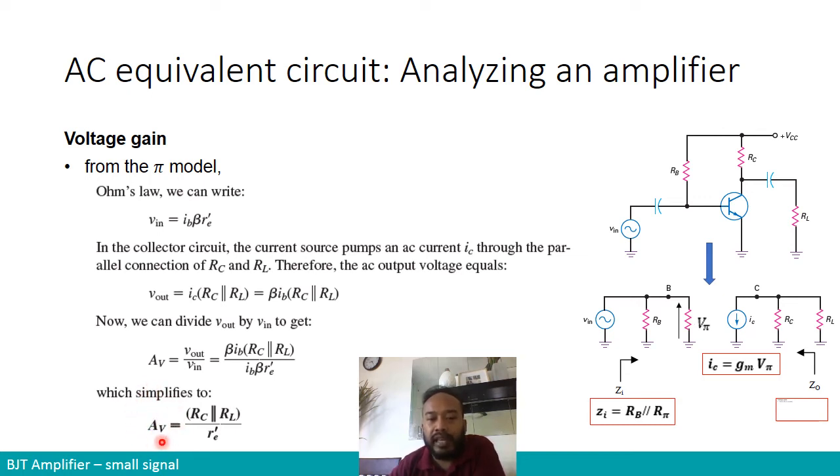And then of course the gain of the amplification, the voltage gain, is just the ratio of V output divided by V input. So this is what we get over here. Depending on which parameter is given, it might vary, but here it shows a very simplified expression that explains exactly what happened in this particular amplifier circuit. So it's not always going to be this. You just have to apply V out over V in, and look at the formula that is provided to you.